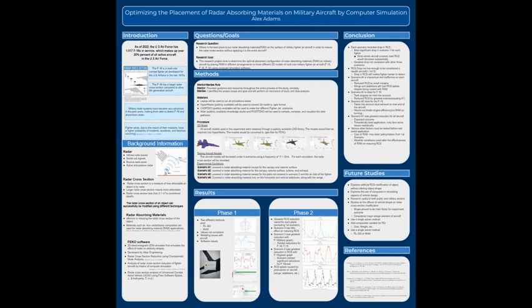Scenario 2 saw the greatest reduction in radar cross-section for the F-16, which was seen in the green graph, but it also yielded significant radar cross-section reduction for the F-18, which is seen in the red graph. And the spikes in the radar cross-section for all three graphs listed there are due to protrusions on the aircraft itself, such as its wings, stabilizers, etc.